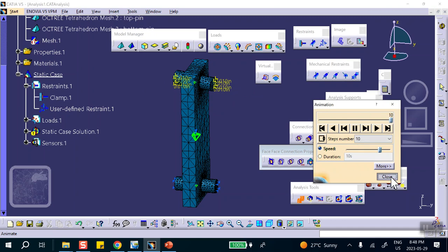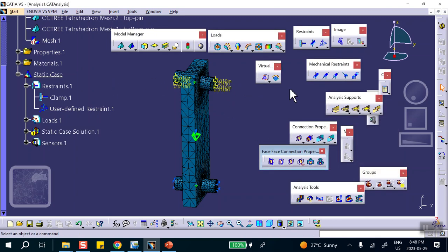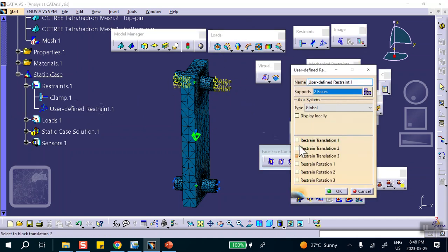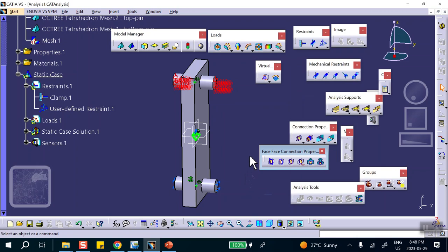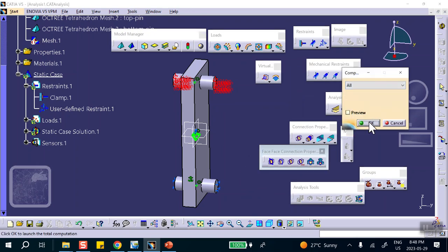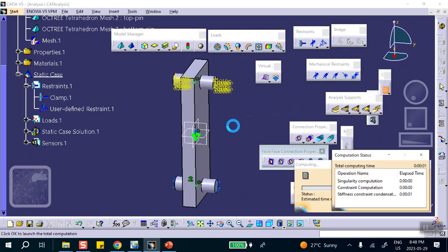So let's stop this thing by not allowing it to move, for example, in direction Y and direction X, okay? Because after all we want to do is to take this thing and pull it up. So double click on this and say, okay, in all three directions, and say, okay, and now run it. It will still bomb out. You'll see why in a minute.